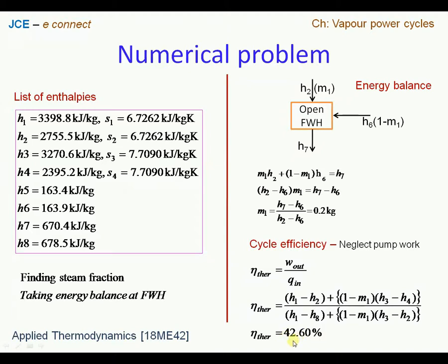And please recall that for a simple Rankine cycle, we obtained somewhere around 30%, and with the modifications on the simple Rankine cycle in terms of the reheat method or the regeneration method, we can always see that the percentage is now rising. And this is a problem where we had a combination of reheat along with regeneration, and we see the rise in the thermal efficiency, clearly showing that the improvement or modification done onto the system is reflected in higher thermal efficiencies.